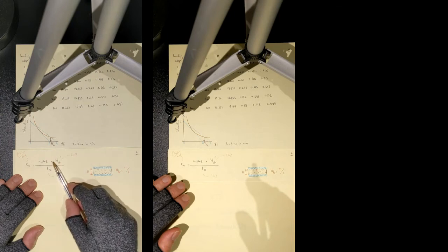If your C sub V is in centimeters square over hour, then your C sub V will be equal to a constant, which is 0.848, multiplied by H sub dr. This is the drainage length. I will tell you what this drainage height or drainage length is. H dr square, this must be in centimeters, divided by T sub 90. Your T sub 90 should be in hours.